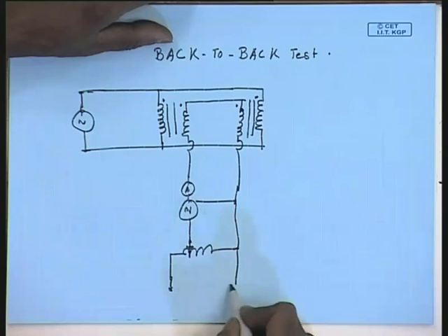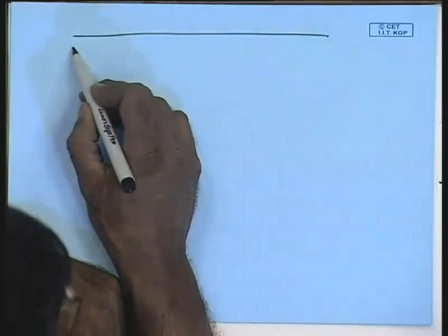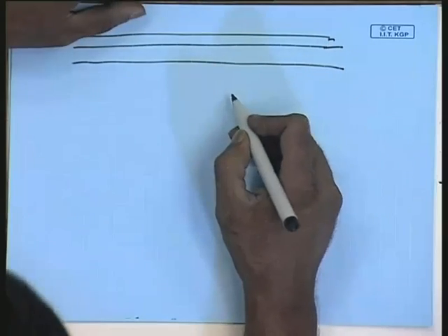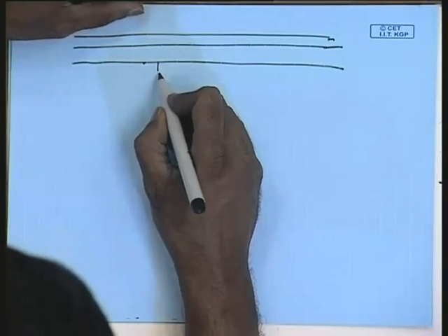A similar arrangement has to be done for a 3-phase transformer now. So, let us say we have a 3-phase transformer. If any particular side is star connected, what we should do? We have to connect those star windings in series, while the other side has to be connected in parallel. So, the following figure shows an arrangement. Let us say this is the 3-phase mains supply line, and you have connected one of the windings in parallel.